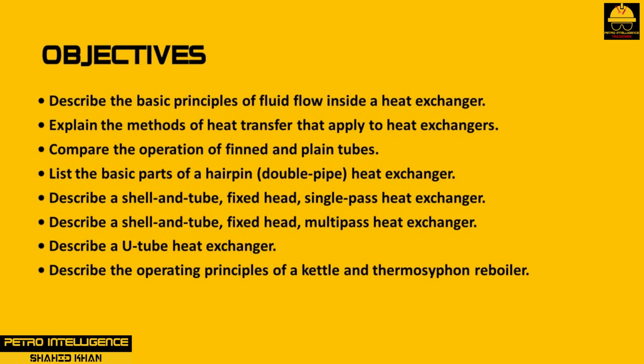Explain the methods of heat transfer that apply to heat exchangers. Compare the operation of finned and plain tubes. List the basic parts of a hairpin, double pipe, heat exchanger. Describe a shell and tube, fixed head, and single pass heat exchanger. Describe a shell and tube, fixed head, and multi-pass heat exchanger.